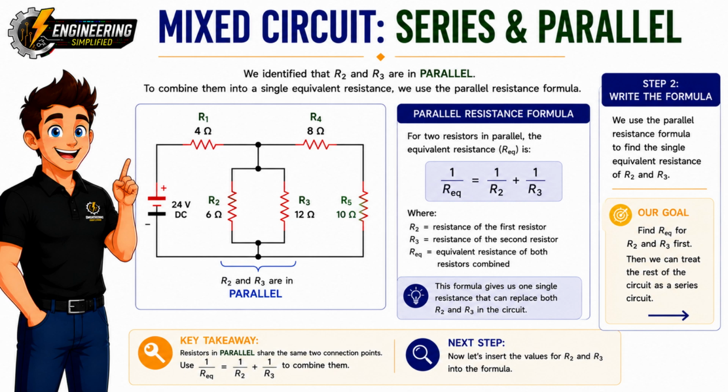Because they share the same top node and the same bottom node, they are connected in parallel. Next, look over to the right. R4 and R5 are connected end to end with no branching between them. That means R4 and R5 are in series, so later we'll be able to combine them into a single equivalent resistance. Finally, R1 sits at the beginning of the circuit, in series with the rest of the network.